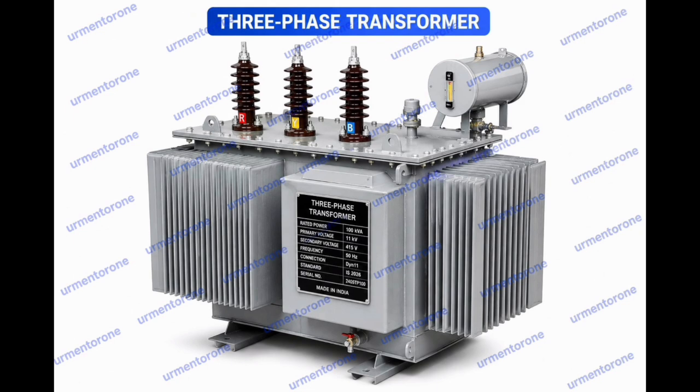Winding configurations. The windings can be connected in two main ways, delta and star. Delta is a three-wire configuration where the ends of the transformer windings are connected in a closed loop. Star is a four-wire configuration where one end of each winding connects to a common neutral point, providing both line to line and line to neutral voltages. Common applications: industrial manufacturing plants, high voltage power grids, data centers, and heavy commercial power distribution.